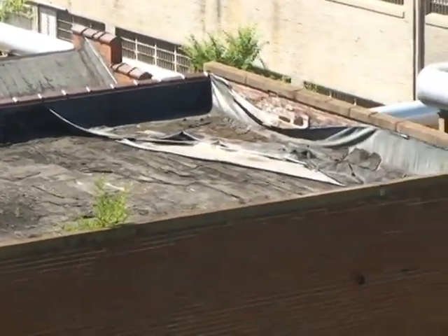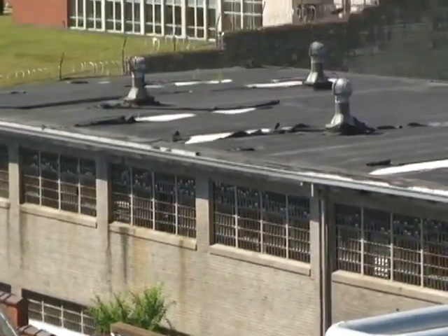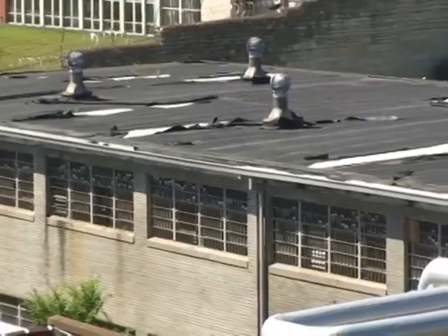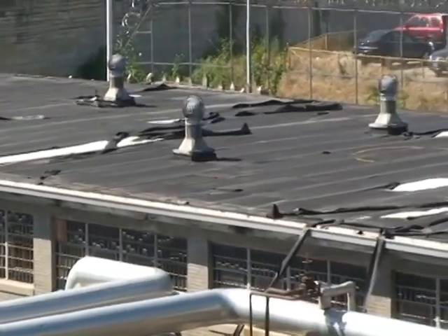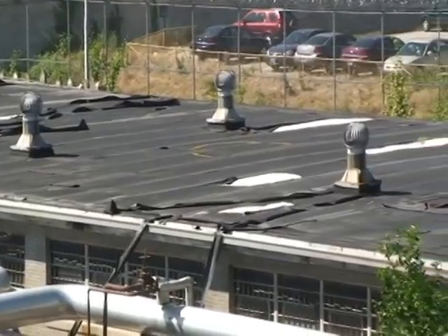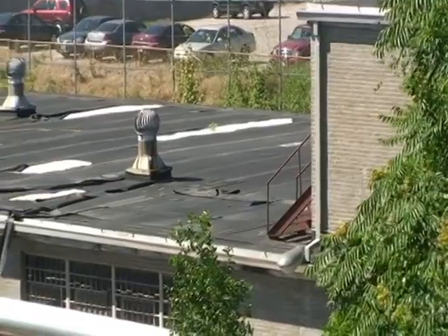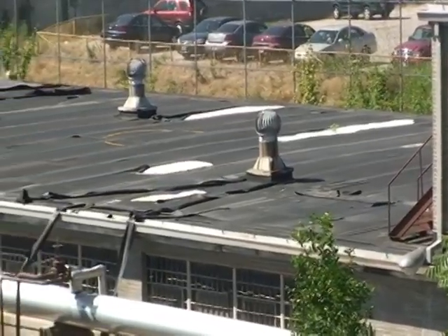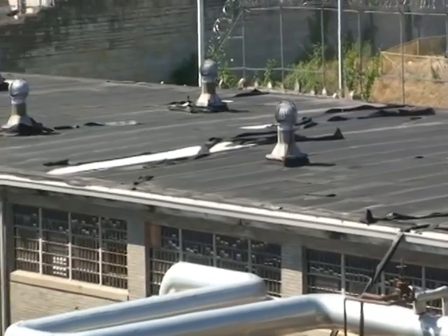Roofing materials in general are considered non-regulated, non-friable materials if they're in good condition. Built-up roofs like this, you can find asbestos in the mastics, the flashings, and the joints underneath the felts. Generally the rubber membrane won't contain it. If you look at the roof vents on this, you can find asbestos in the black mastic where it seals the joints up around there as well.